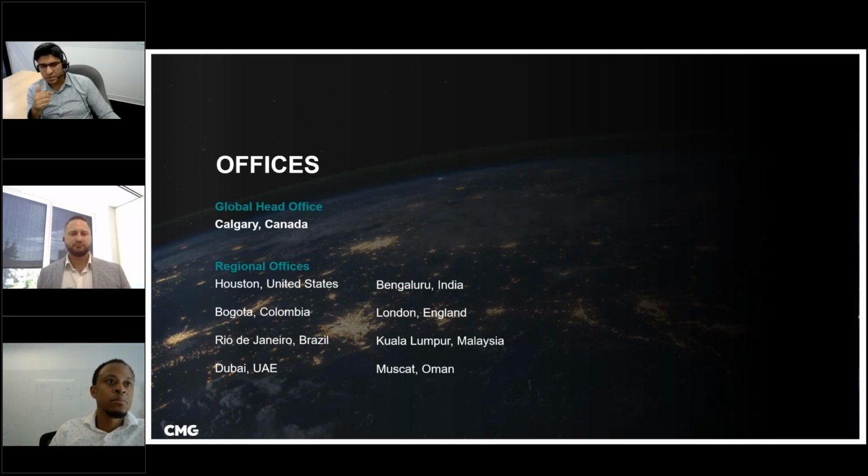I didn't present the result, but we found that just a few days after the start of the forecast period is the best time to start injecting, and the sooner the better. But in total 9 parameters were introduced to CMOST to change at the same time, and CMOST will use very complex experimental design algorithms to first generate a very optimum solution space and explore the space first, and then take it from there and optimize it. In this case, 9 parameters were introduced to CMOST for optimization.